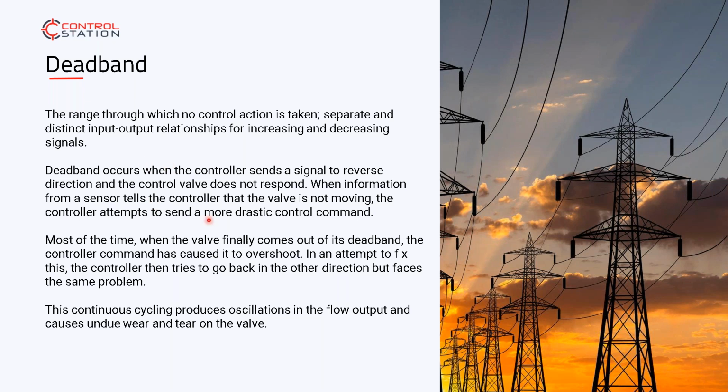Deadband is when we ask the valve to move and it works fine, but then when we move it in the opposite direction, it has to overcome a degree of slop in the valve, looseness in the connections, which can be caused by a lower quality valve. It can be caused by wear and tear on the connectors, the buckles, the linkage arms. It's not necessarily a friction issue, because the friction issue will remain there all the time. But deadband